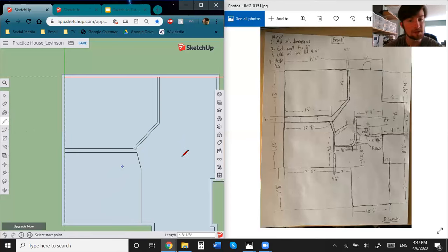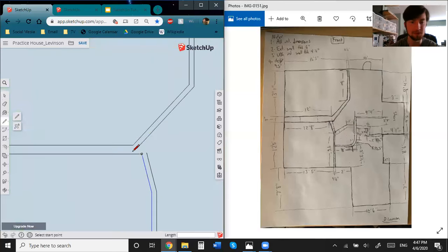And it looks like I can select tool, select these 2, this line, and hold Control or Command. You see the plus comes up next to my mouse. And click that second line, and we will offset, clicking on the lines, going out to the right 4.5 inches. There.